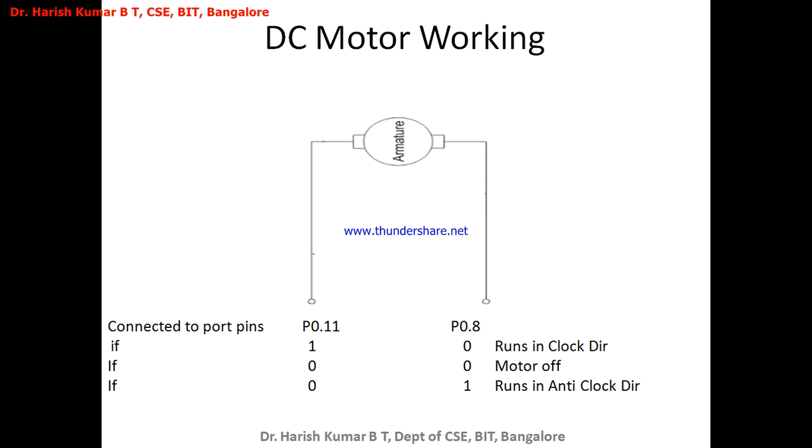Now I'll show the simulation of these things, but when you come back to the college, all these programs you have to execute on a hardware kit. The kits are supplied by the ALS, and there all these connections are made already. Now the stepper motor is permanently connected to P0.11, and the another terminal of the DC motor is permanently connected to P0.8. Hence I've taken the same thing.